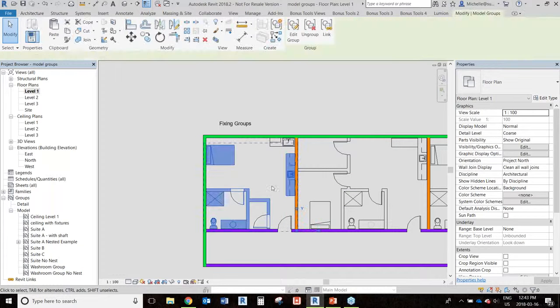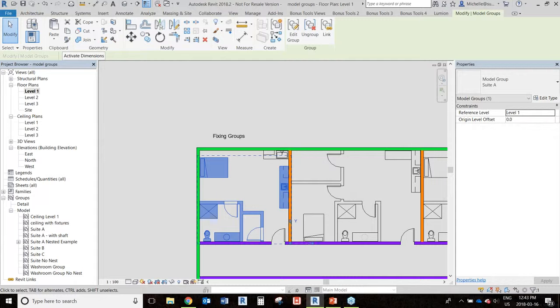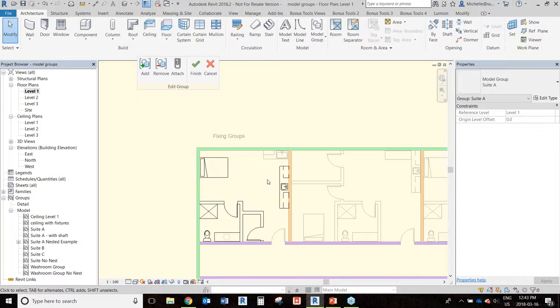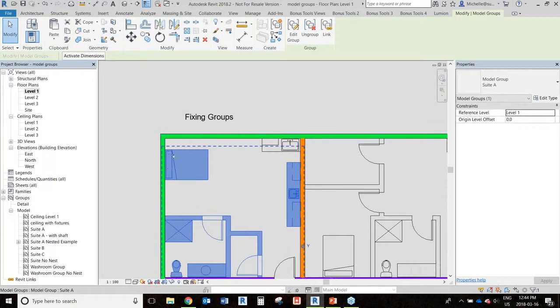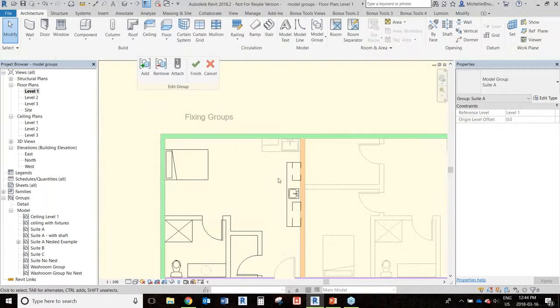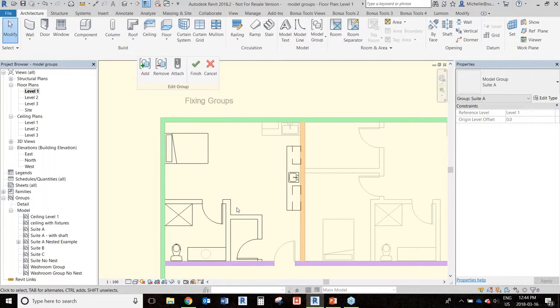And I've only done this once or twice. I used to do this with projects so that you could then show consistent dimensioning and annotation. The problem that I really had with that one was that it involved using a lot of reference planes to some extent, because, for example, if you want to attach any detail within here, it has to exist within this model and has to have everything referenced within it.